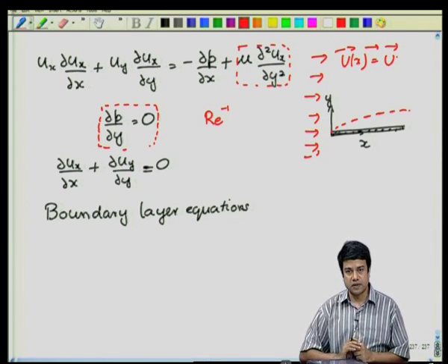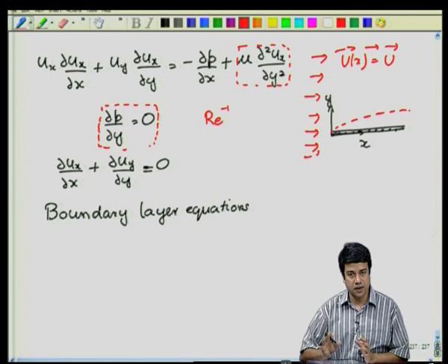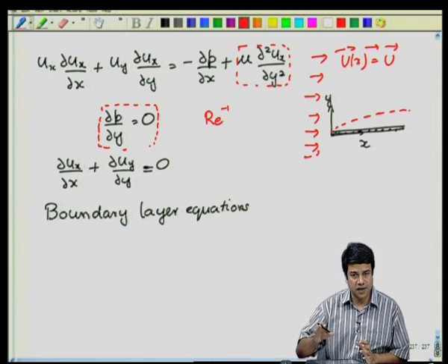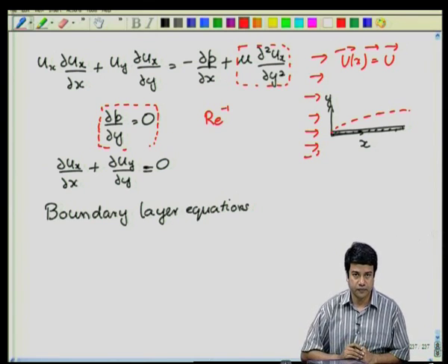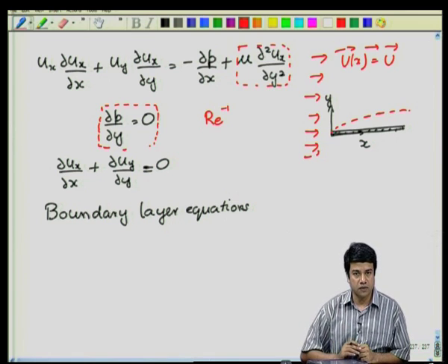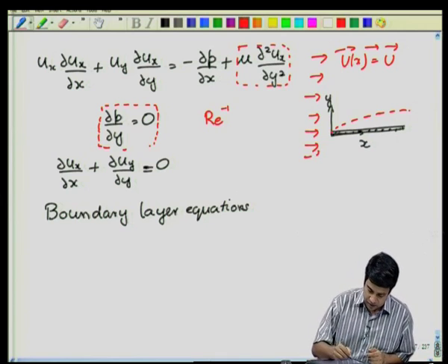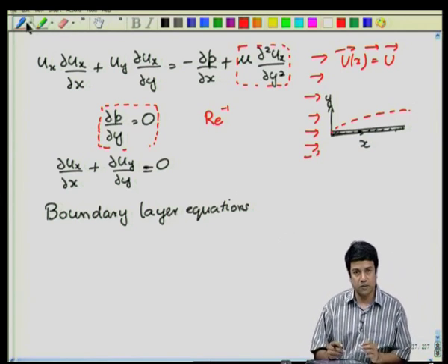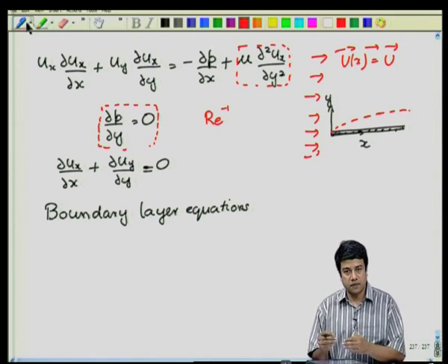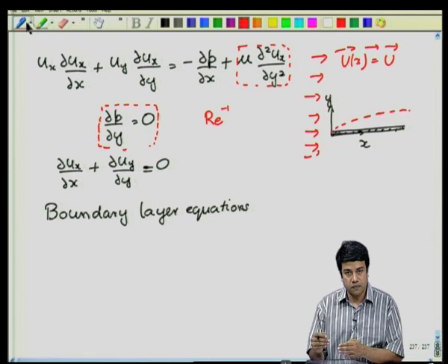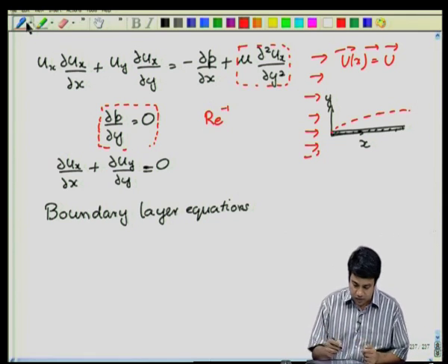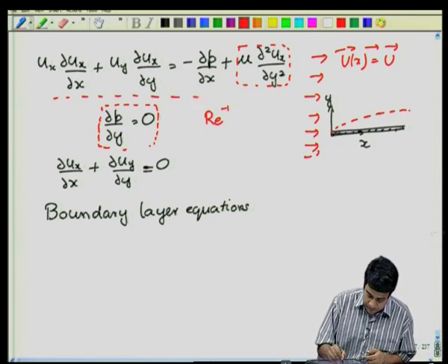Far away from the surface, but as we will see, there are other cases where there may be either acceleration or deceleration of the free stream flow far away from the surface, in the x direction. So, for the outer flow you require that the flow has to satisfy the equation. For the outer flow there will be a smooth transition from the boundary layer flow to the outer flow if the outer flow, when viscosity is neglected, also satisfies the same equation.